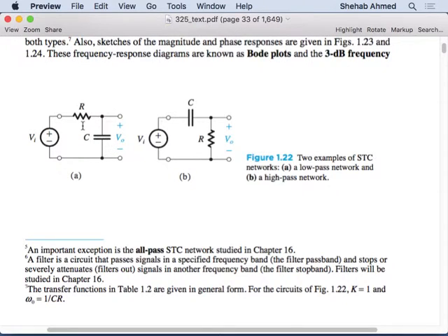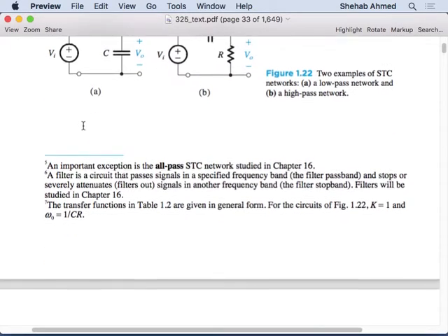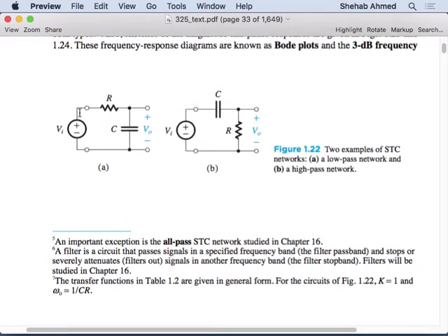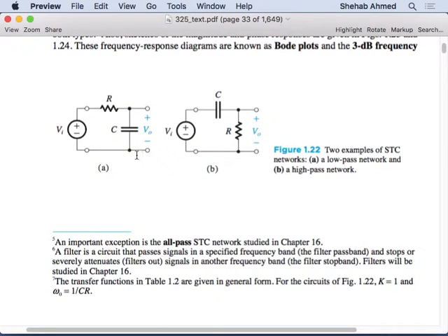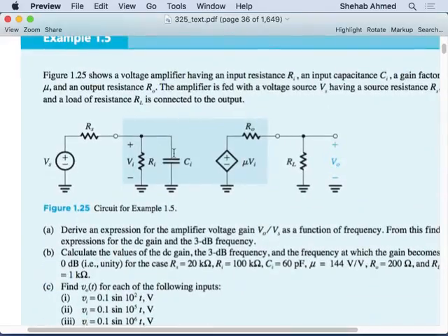Because it's not a simple R, RC, then we have some gain. And we will go through that. We will look at how we will utilize that. Okay, so this is the objective, right? Since we have one C, it's obvious, and this C actually is also in parallel, right? If you see here, this capacitor is in parallel. If we go look at the amplifier model that we're playing with now, the capacitor is also in parallel. So it tells you that it's going to be similar probably to the low-pass filter, right? But we are deriving the exact relationship in the example between V output and Vs.